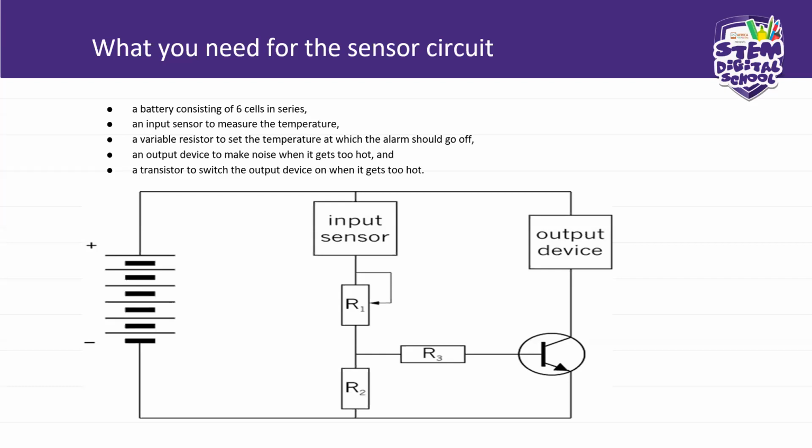3 would be somewhere in the middle, okay? So that's just moderate temperature. So if we set our variable resistor there, your circuit is going to make noise all the time. This buzzer will just go off all the time, even if it's just warm, if it's comfortably warm. But if we set the variable resistor to its maximum, to its lowest resistance, in other words, its maximum value is the lowest resistance. So it means when the temperature is at its highest, then the alarm will go off.